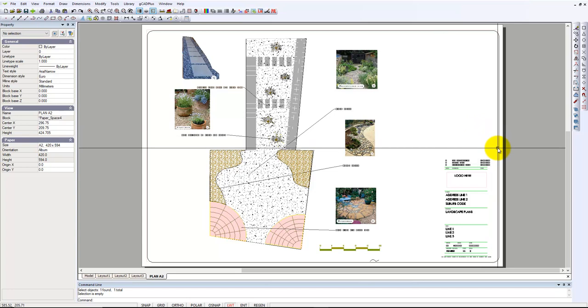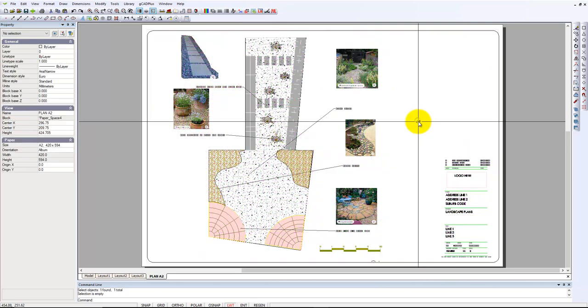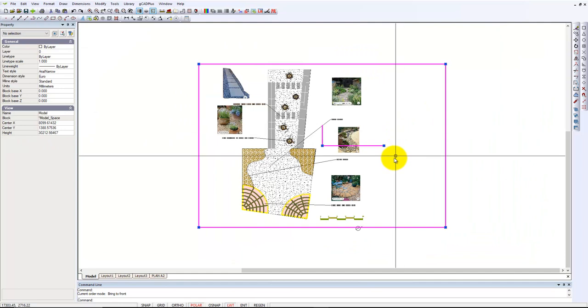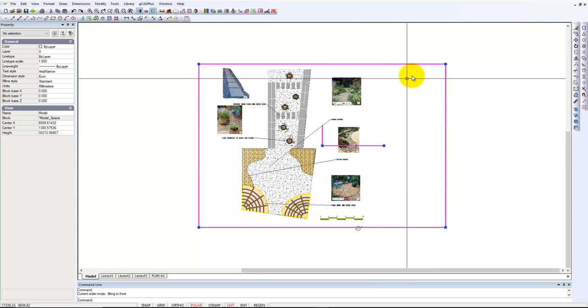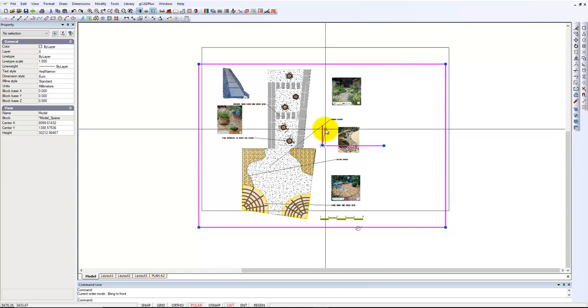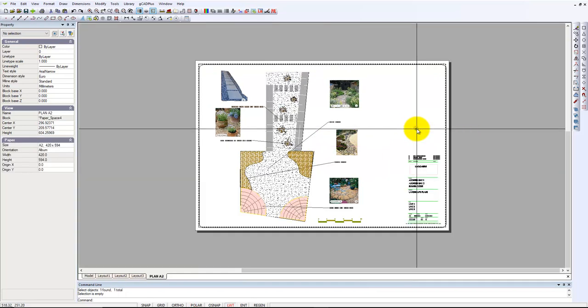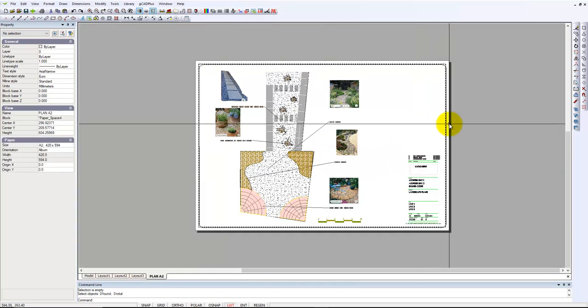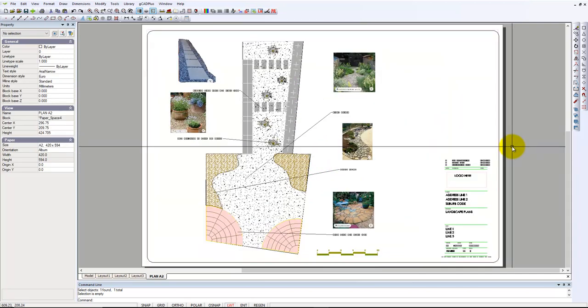If I pick the floating viewport, notice that it's got a view scale of close to 50, so you might want to fix that at 50 and say yes, this is fixed scale. And it's obvious when we go into the porthole that positions the drawing, I can no longer size that. I am restricted to that fixed viewport window. Well, that's probably too much for us now, but let's hope that helps our new beginners.